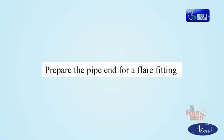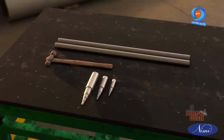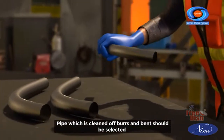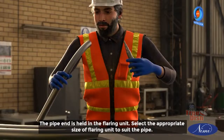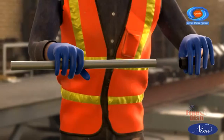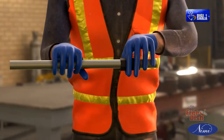Prepare the pipe end for a flare fitting. Flaring with block and punch tool. A pipe which is cleaned of burrs and bent should be selected. The pipe end is held in the flaring unit. Select the appropriate size of flaring unit to suit the pipe. Sleeve and cap nut should be assembled before flaring.